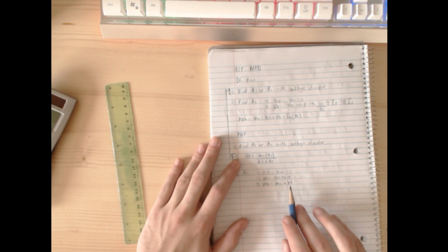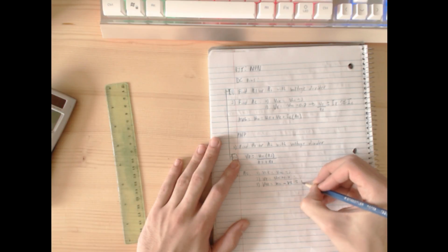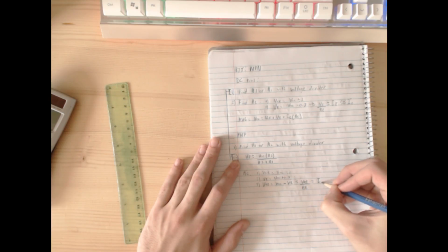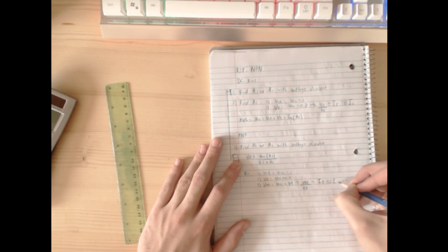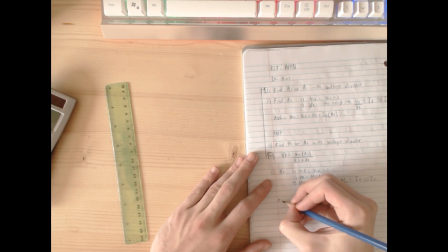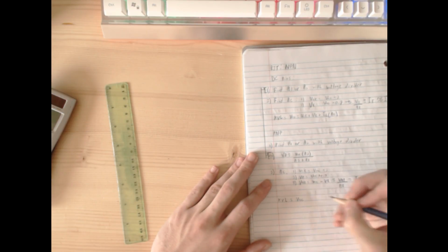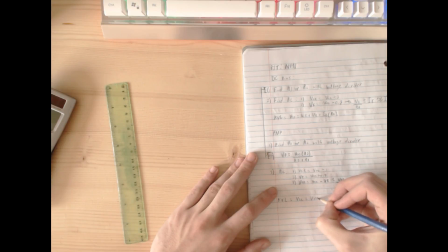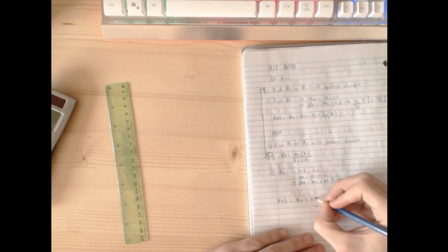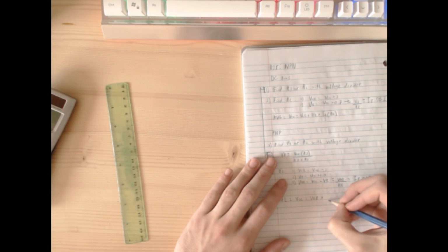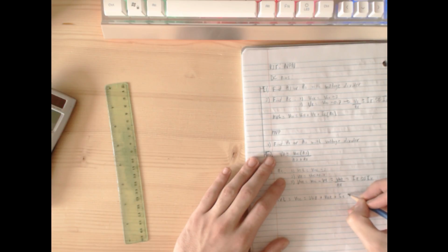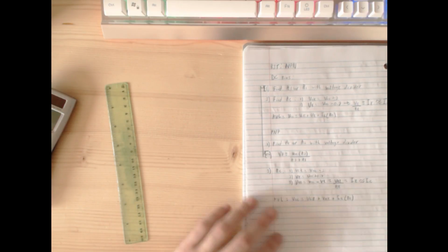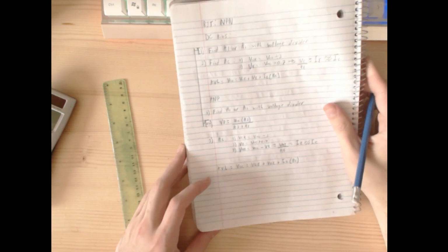This is when you're measuring VE, it's relative to ground, which is equal to VRE divided by RE is equal to IE, which is equivalent to IC. And you do KVL, which is VCC equals VCE plus VRE plus IC times RC. So that would be for both.